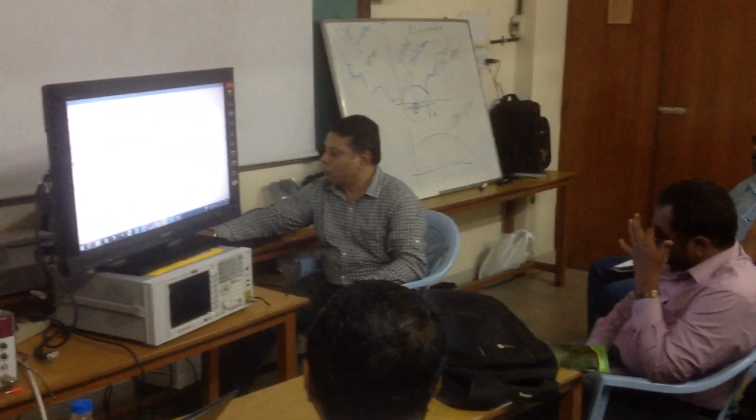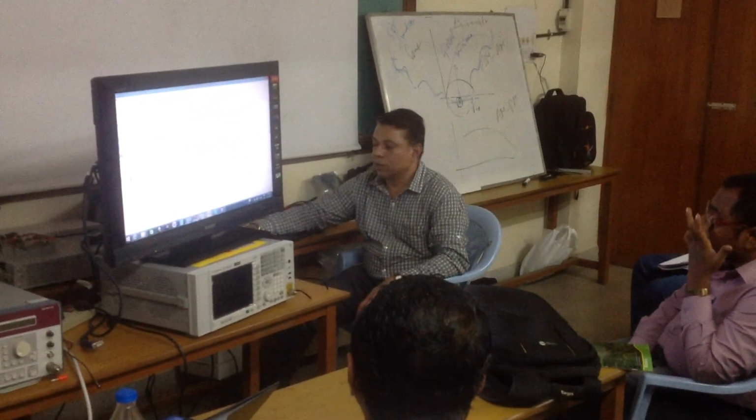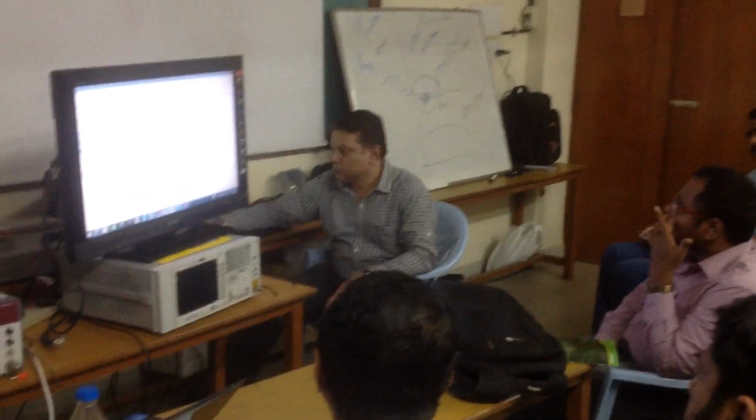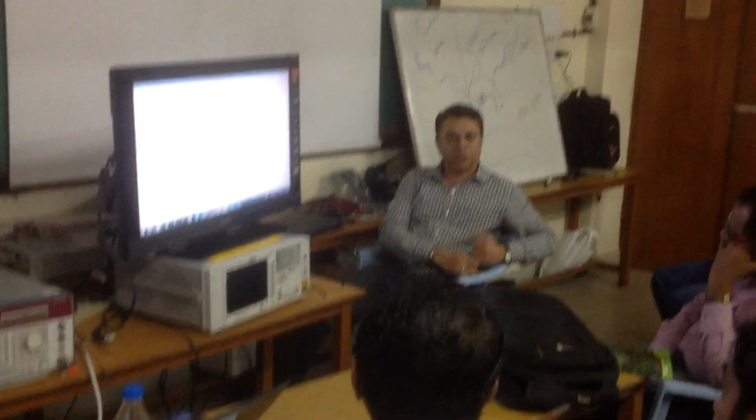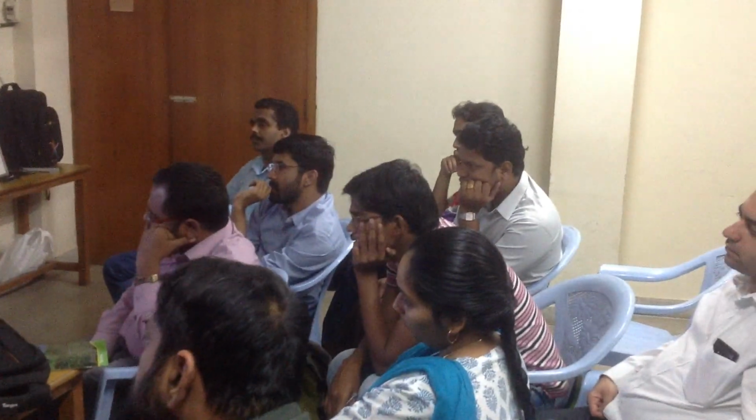So output return loss is good, but input return loss is not good. That's where I was saying the only solution is either you use an isolator at the input, which will give you good return loss, or a balanced structure. That's the only way. Now, maybe if you run the optimizer, you give up some noise figure, you may get a good match at the end. I have not done that.